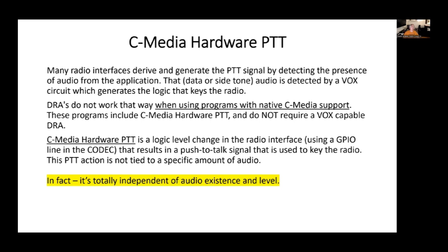Basically the program is written so that it changes the state of a GPIO in the codec, and that change of state biases a transistor, and that push-to-talk signal is what is used then to key the radio.